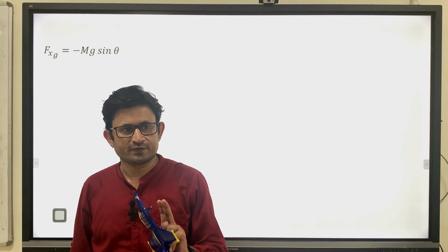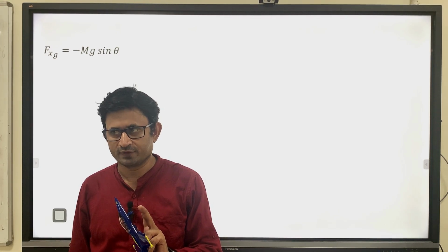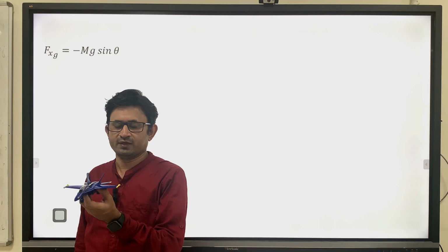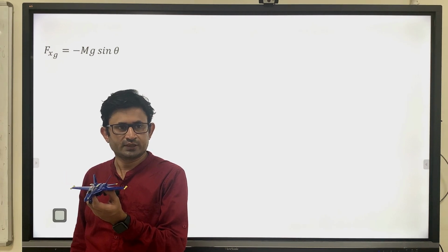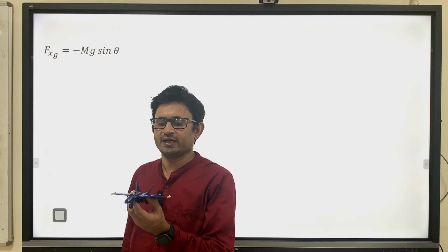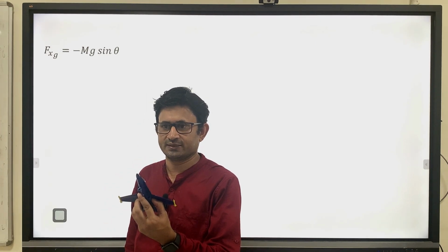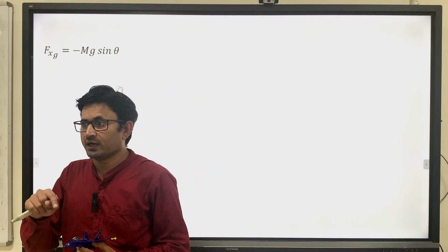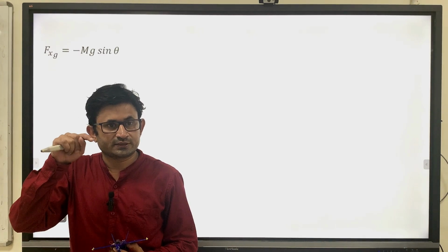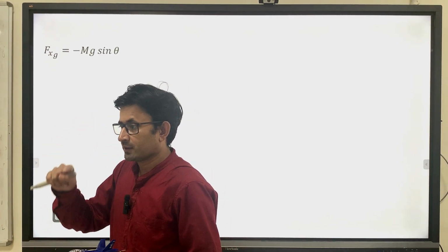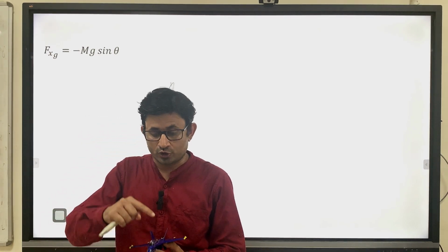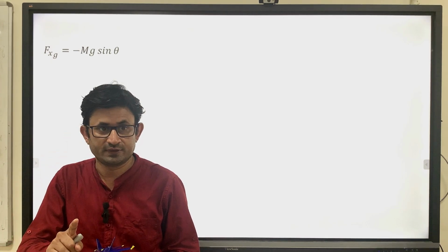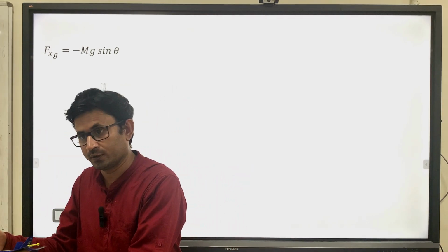First we will understand the gravity force. So let's say we have a model in our hand. Gravity will always act in the downward direction. Okay. So let's say you have rotated by some angle theta. What will be the component along the x-axis? See, I want each and every force, whether it is aerodynamic force, gravitational force or propulsion force, in the body frame. So all the forces I will resolve in the body frame. Then I will sum up and apply Newton's law. Okay.